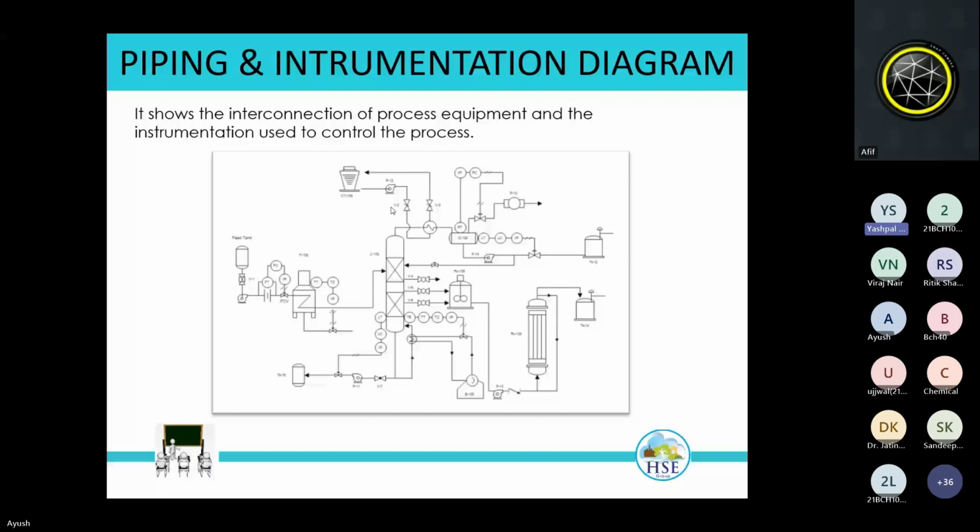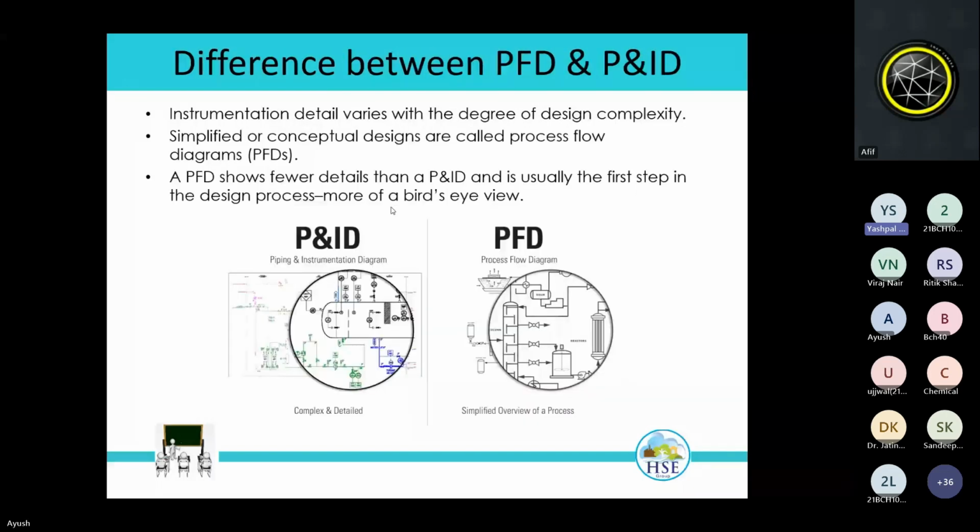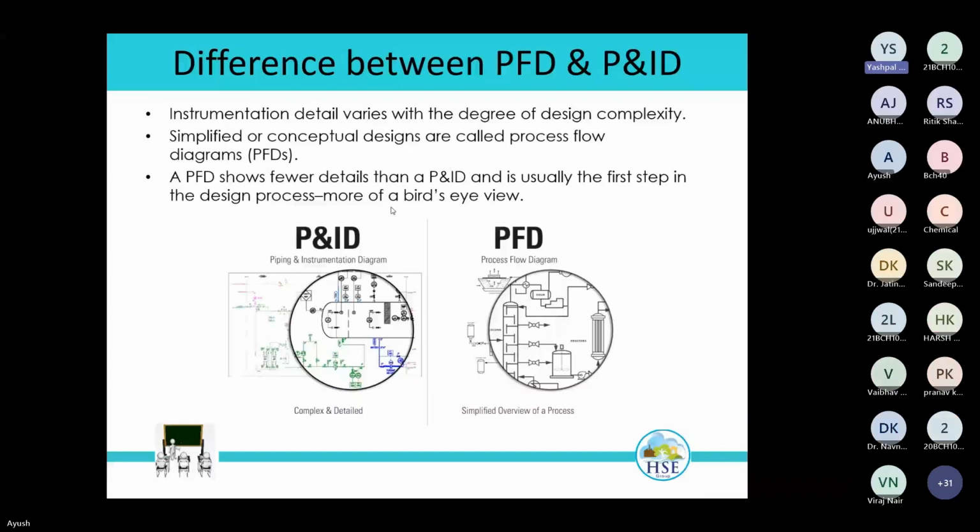All are normally used, but for final design and drawings mainly we use the P&ID for all the explanation. Normally, chronology is like that. First we prepare the block flow diagram. From the block flow diagram we prepare the process flow diagram. In the process flow diagram we define the equipment requirement, and capacity of course can also be defined in the process flow diagram.